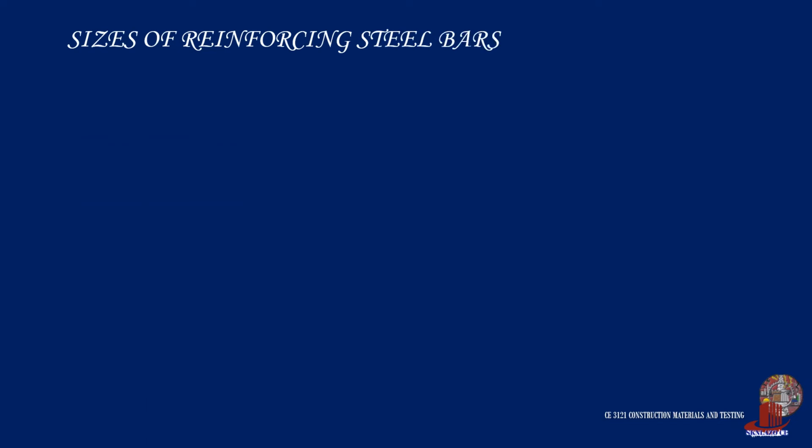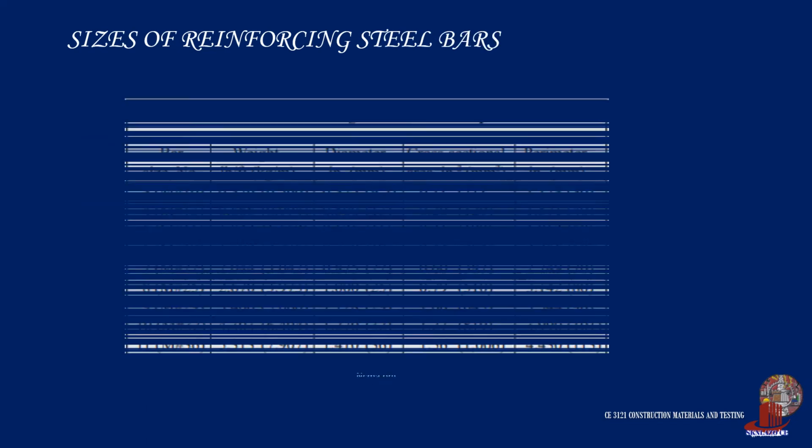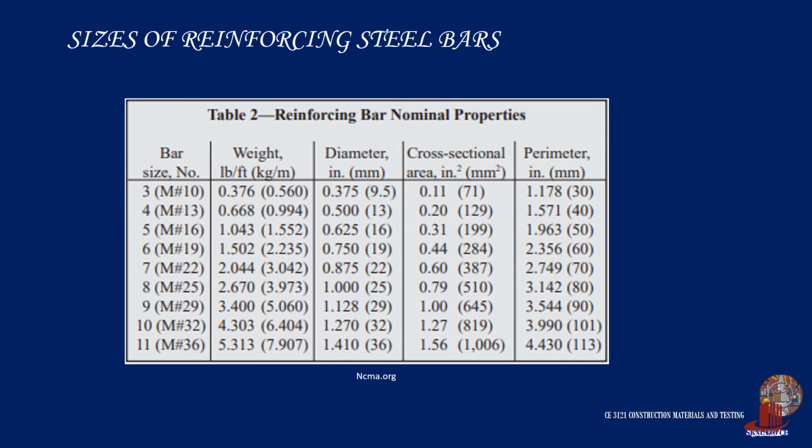Sizes of rebars are given using their diameters. From the chart, nominal properties of steel rebars are represented as they are useful in both design and construction. Although the most used minimum size of rebar is 10 mm, there is still a smaller size of 8 mm or D8, most often used for grille works. The largest diameter which can be used in design is 36 mm.